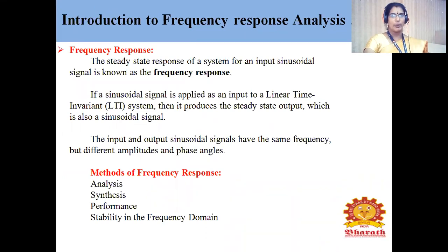Let's begin with frequency response. The steady state response of a system for an input sinusoidal signal is known as the frequency response. If you apply a sinusoidal signal as an input to a linear time invariant system, then it produces a steady state output, which will also be a sinusoidal signal. The input and the output sinusoidal signals have the same frequency but with different amplitude and phase angles.